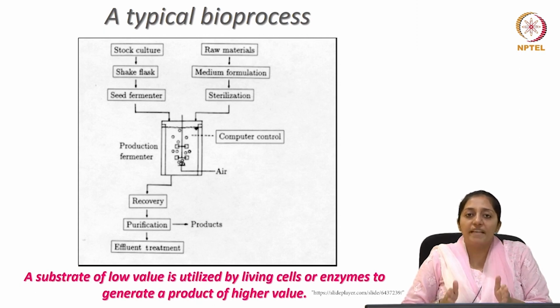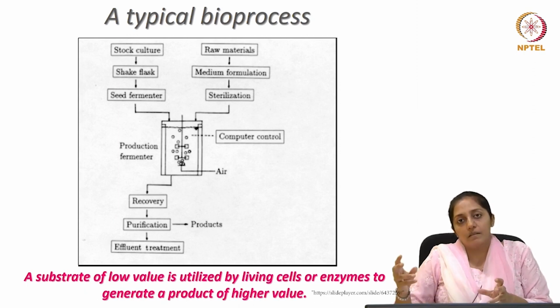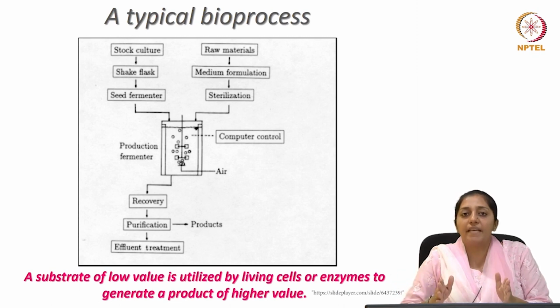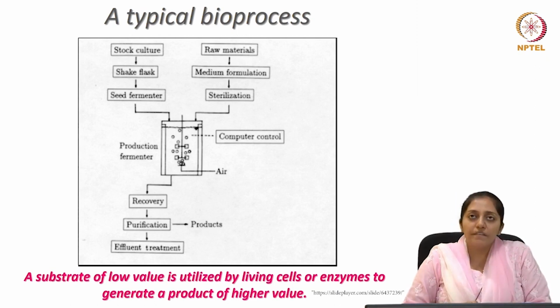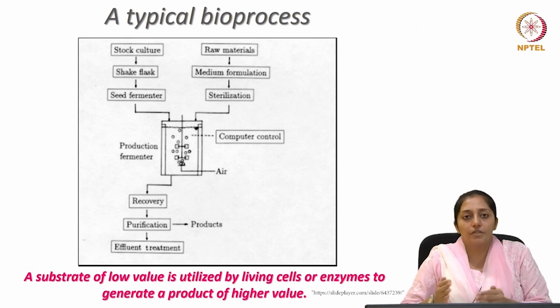So in order to maintain those required set of conditions at their optimum values to maximize the productivity or the production rates, there is an automated control which can help in maintaining the culture conditions of this controlled system environment at its optimum. Generally, you will find there is pH, dissolved oxygen, temperature. These are the key parameters which can be controlled in a reactor.